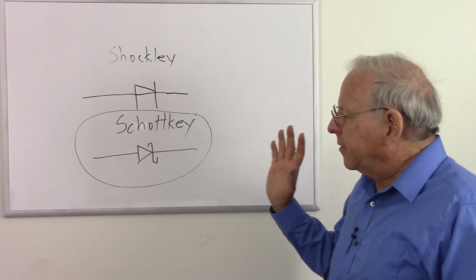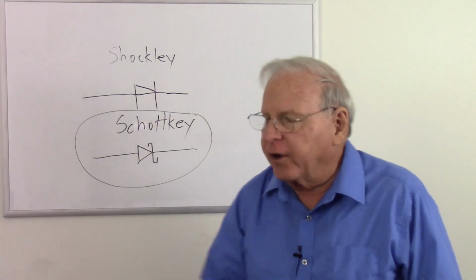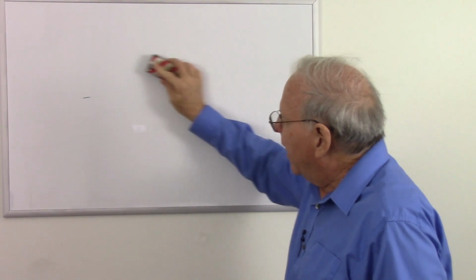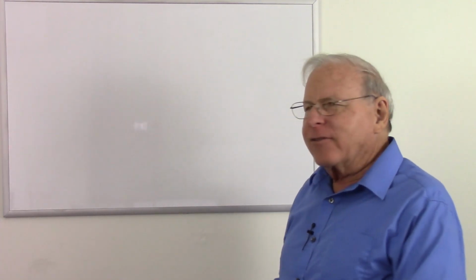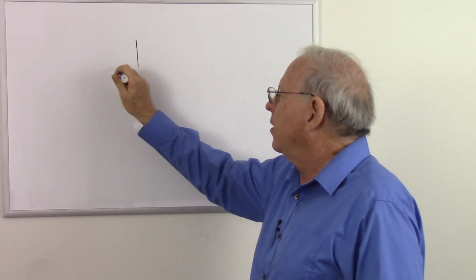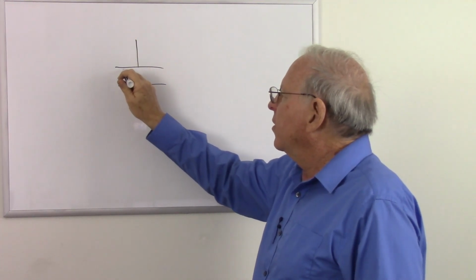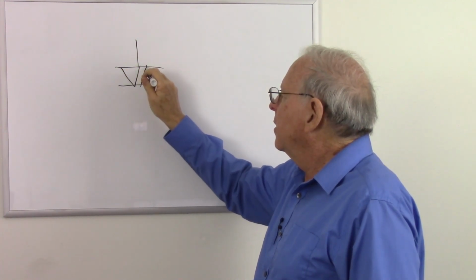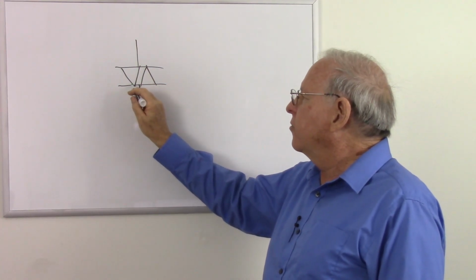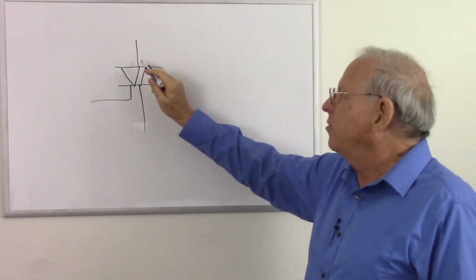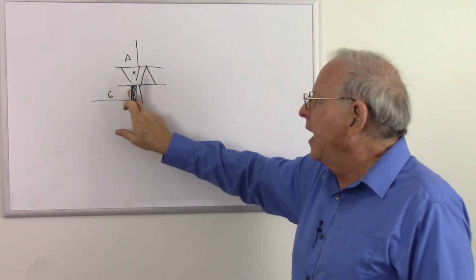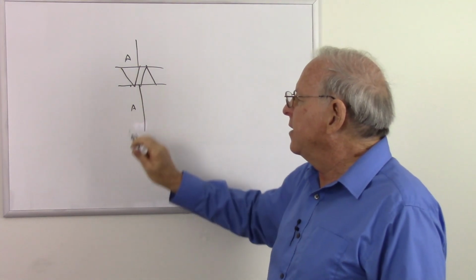Now I should have talked about the diac, but I guess that's appropriate here too, because it's closer to the SCR or the triac, but it sort of acts like a Shockley diode that works both ways, so it could be appropriate here. Here is the symbol for the diac. I forgot to give the symbol for the triac. Well, there's the symbol for the triac. So we have two anodes and one gate. We remove the gate, we have a diac.